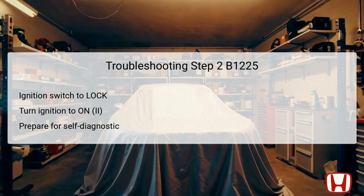In the second step of troubleshooting, you'll need to turn the ignition switch to the lock position, then back to the on second position. This step serves to power up the vehicle's electronic systems, setting the stage for a careful self-diagnostic function of the in-car temperature sensor. The process of switching off and turning the ignition back on is often necessary to reset various components within the vehicle, preparing them for diagnostic testing. This action helps ensure that the climate control unit is operational and ready for evaluation.